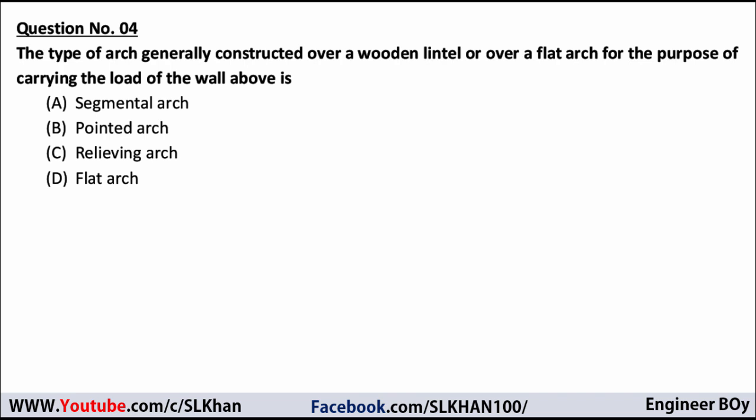The type of arch generally constructed over a wooden lintel or over a flat arch for the purpose of carrying the load of the wall above it. Is it segmental arch? Nope, it cannot be segmental arch. Segmental arches are never constructed over a flat arch or a wooden lintel, so that's not okay.